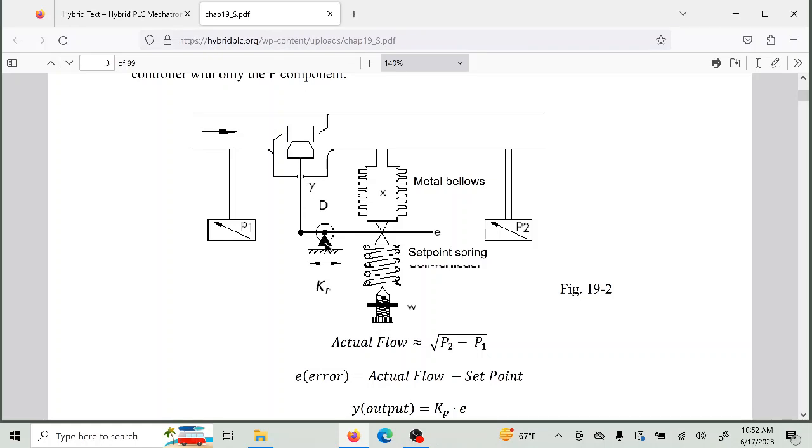Now, if we move this little fulcrum, we can move it back and forth, and we can also change the tension on the spring. Either place will cause this system to act differently. If I move the fulcrum to the right, a little bit of action over here causes more action over here. If you're on a teeter-totter, you understand that concept, because usually the long guy wins.